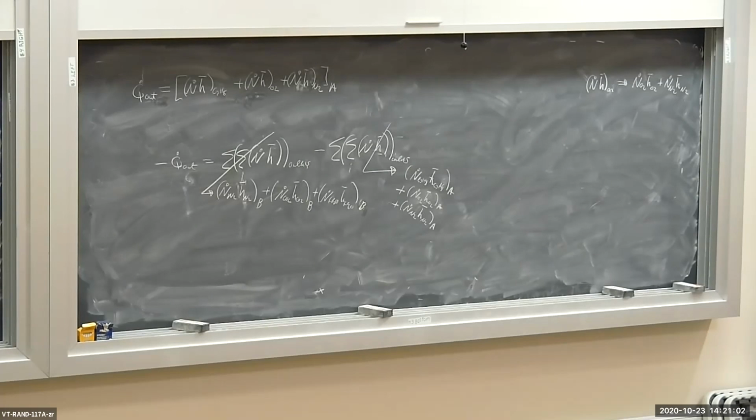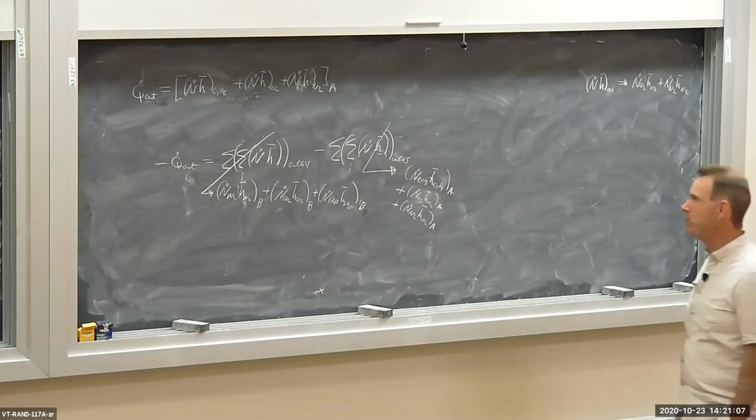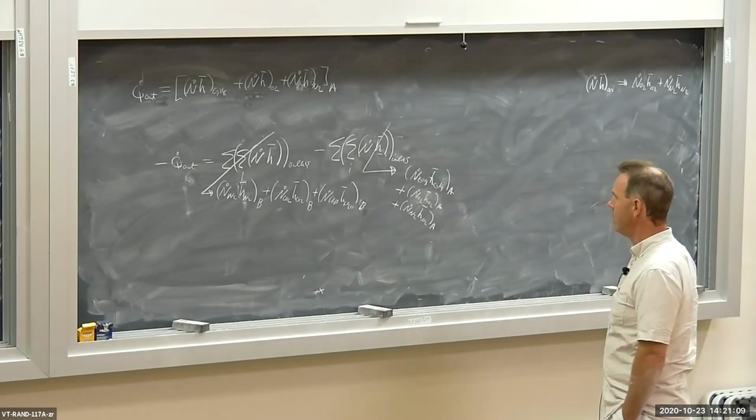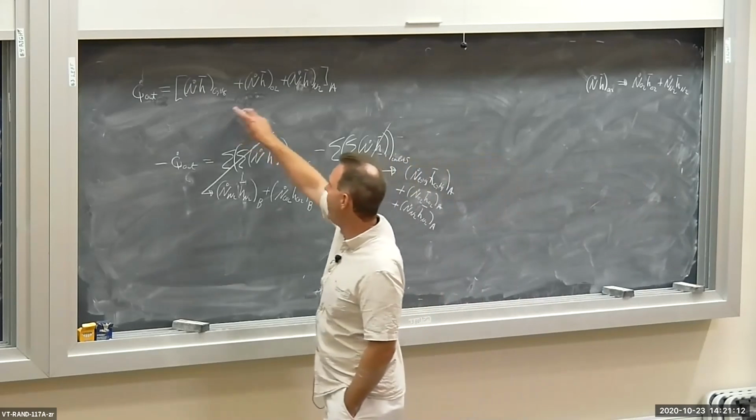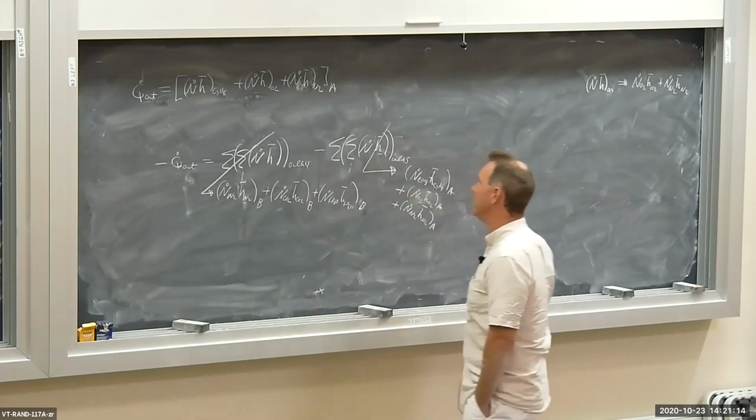The propane and the air are at the same state, so I can lump them together, since they're at the same temperatures and pressures. That's why I can include the fuel and the air evaluated at the same state.